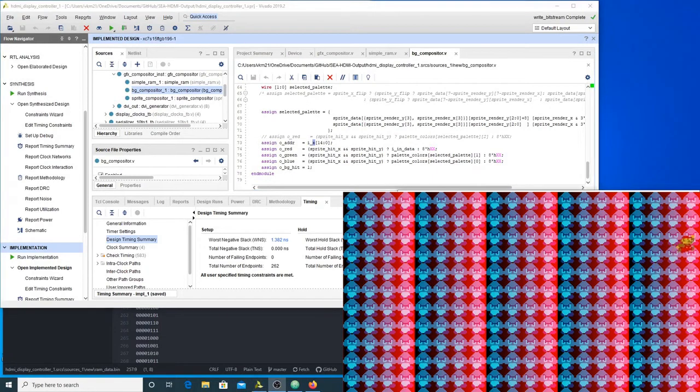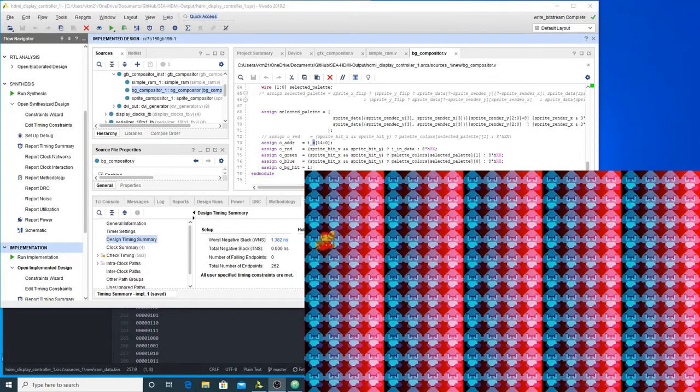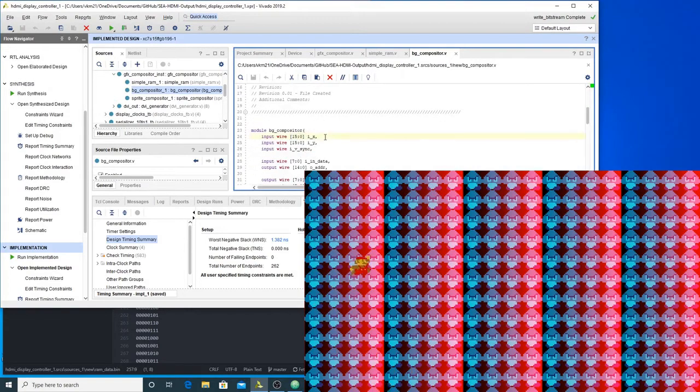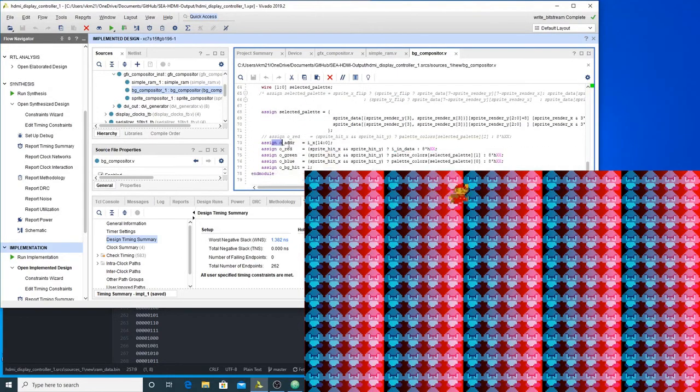coordinate. So as the system scans left to right, it's going to look from left to right on every row of the pixels, and the X value is going to keep increasing as it goes to the right. We're only going to capture the first 15 bits of it because we only have a 15-bit memory. The X coordinate here is actually a 16-bit number, but our memory isn't that big. And this was just a little hack to make sure that this works.